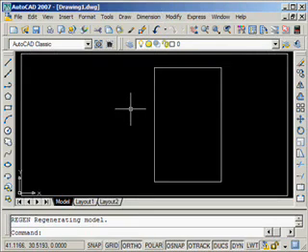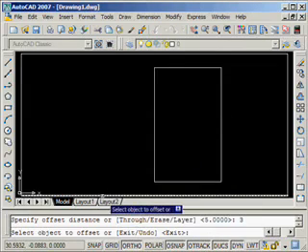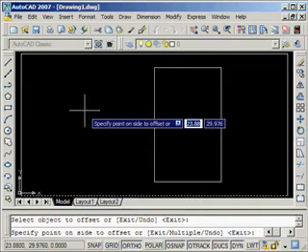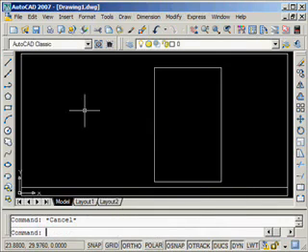All right, the next thing we want to do is draw in the garage. We're going to use the offset command again, just like we did with the house. I'm going to type in offset, hit enter. It's asking me to offset what distance. It's 3 feet from the south edge of the property line, so select that line, click up to offset it to the north side, hit escape a couple of times to clear that command.